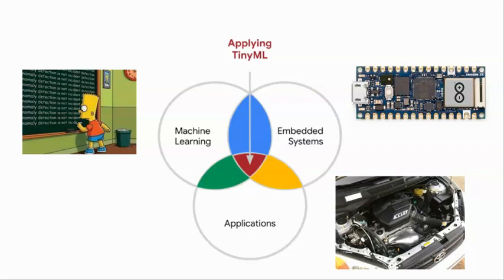So using k-means is not the only one. You could use the local outlier factor, isolation forest, and so on. You can also use classification models such as the support vector machine, or maybe random forest or neural network. All of these can be trained to directly classify engine operating conditions as either normal or there is an indicative sign of a knock.